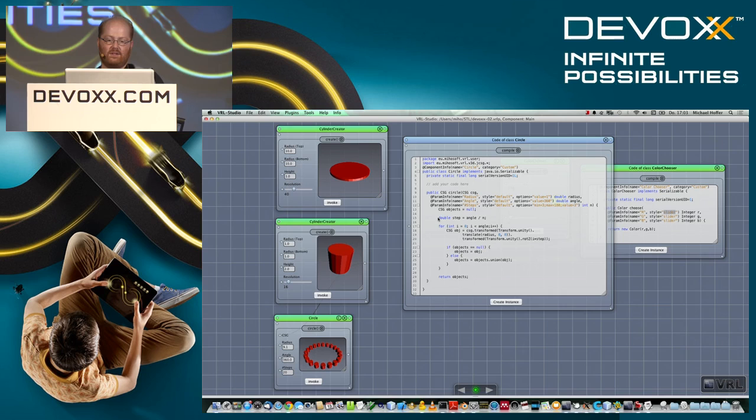Basically what we do is we're giving it a radius for this circle that we're trying to create, then an angle. In our case, we're using just a full circle. And then you give the number of copies of the object. And of course, here the first parameter is the actual CSG object itself.